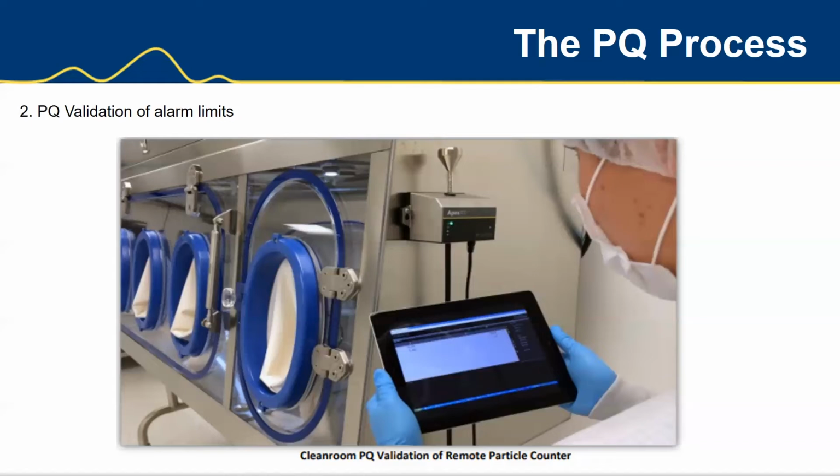You can validate that. You can go through the process and validate that yourself. And there's a way of doing it. I've done it. So making sure you have statistical process control events, X out of Y events in there, and you understand the probability of the level of X out of Y events having on the product. When we see spikes in particles from particle counters, that doesn't mean we're going to see viable counts. If the filling line and the air barriers are working correctly and the operators are not present, then the probability of viable particles in this alarm that's triggered is extremely low. I would probably say 0.